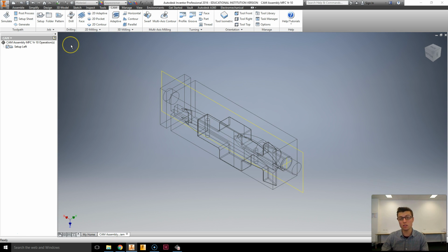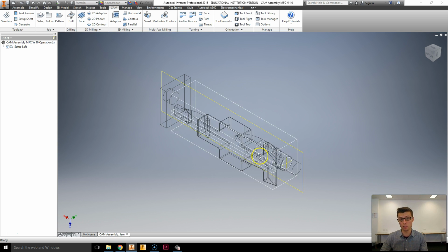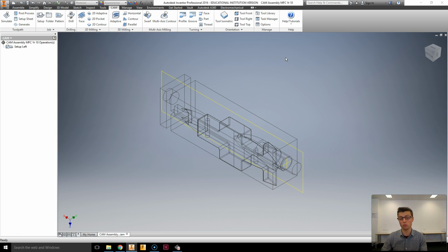The next thing we're going to do is actually do something called a CAM cycle or a program. Basically, there are these setup cycles or systems or programs that you can apply to your CAM setup. What they do is tell the tool or guide the tool to follow a certain path, which will then have an outcome. So this would be how you would face some material or cut away some material to a certain shape. There are different types of cycles. It gets quite complex. We're going to just cover what we need to use in this particular tutorial.